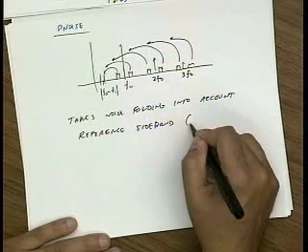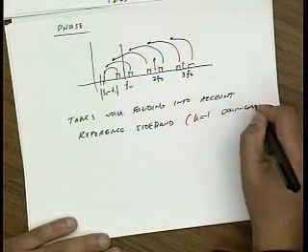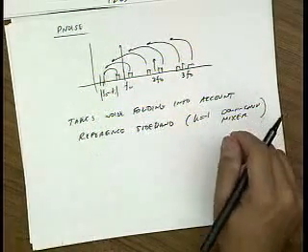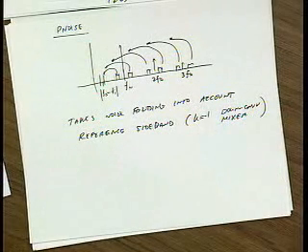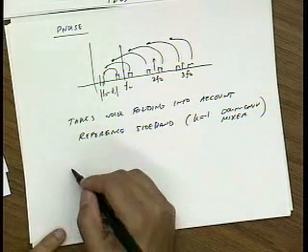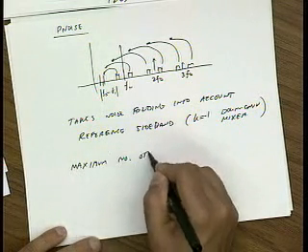For instance, K -1 for a down conversion mixer. And you have to specify the number of harmonics. I think it calls it, is it the maximum number of sidebands or the number of harmonics? Maximum number of sidebands? Yeah. So you also have to specify the maximum number of sidebands.